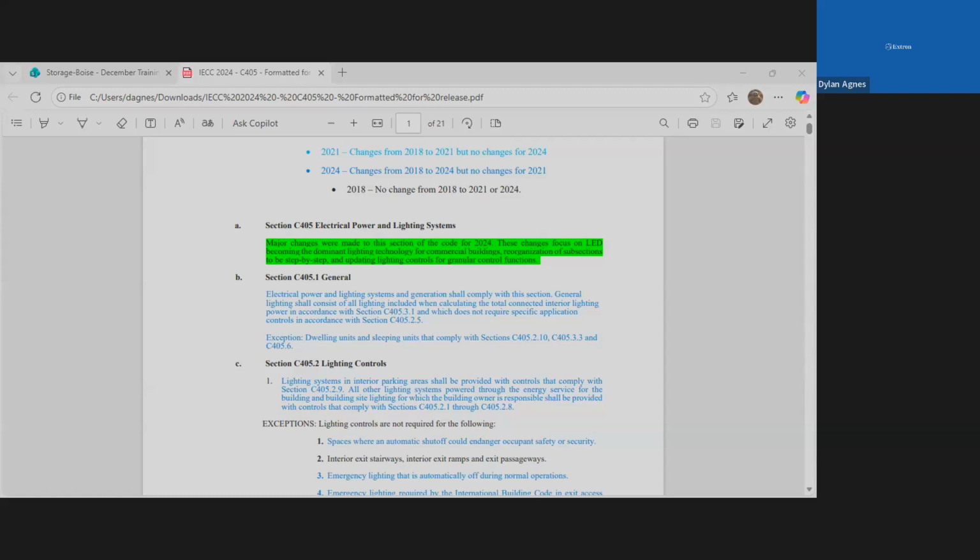So you have to measure those impacts. Same thing with snow load on a roof: if you have a very high insulation value on the roof, you better make sure your snow load calcs are really in line, because that snow's not melting away from excess heat escaping the building. We did have some schools in Idaho that had their roofs collapse when they added extra insulation. Not an issue for new buildings, but for older buildings, sometimes there are consequences.